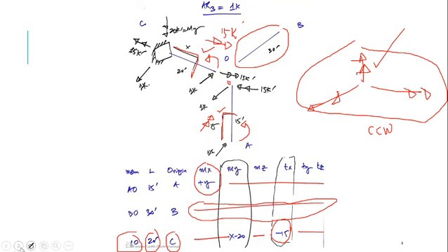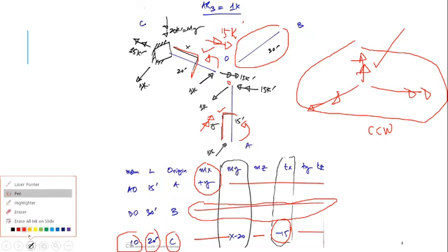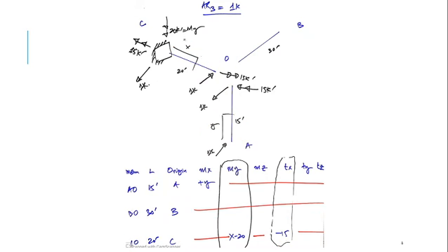Okay, next, I have to find this moment, which would be resisted here with upward, and you know this is counterclockwise, minus 20. This one kip also forms a moment here, and it is anti-clockwise. You have to balance it with a clockwise, 1 into X, so it is plus X. So I have constructed this table.